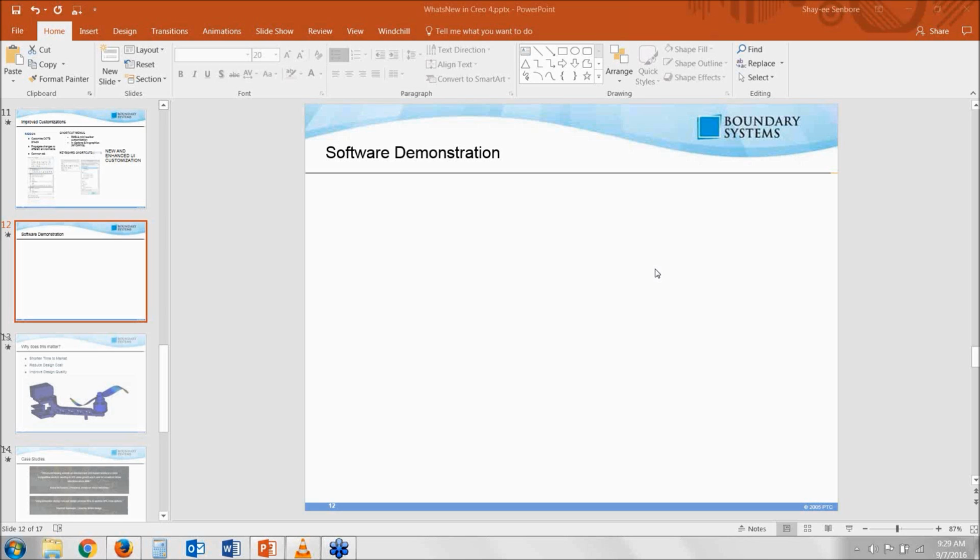In the case of non-Stratasys printers, you can still do many 3D print items inside of Creo. You can still check for printability validation. You can still position items. You can still test your models. You can still do many things that you would do if you were printing to a Stratasys printer. The only thing you would not be able to do is click print and have your printer start to operate, since it's non-Stratasys. So what would then happen is you would eventually create an STL file at the end of all of that, and then load that STL file to your printer and have it go.